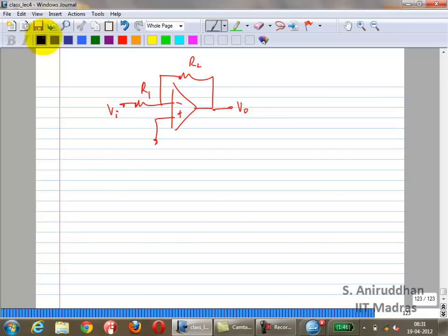There can be some gradients in the process, the way that things are fabricated. Because normally these things are stuck in a furnace, there may be a temperature gradient. Usually the diffusion happens from, it may not be uniform, may come from a particular direction. There are lots of things. Over a chip, you can have a gradient in any direction. You don't know, right? Somebody might turn the wafer and put it in for one particular layer. So you want to take care of these things.